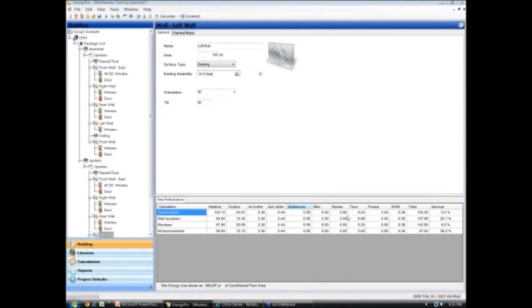What Compass does is it can read the Energy Pro models and actually extract the information out of those Econ2 reports. It's an XML file, and it uses that information to calculate the rebate amounts and the other information that we need for administrative purposes. So that's all there is to it. There's nothing to buy. There's nothing to subscribe to. If you're not participating in the program, then Compass doesn't apply to you.